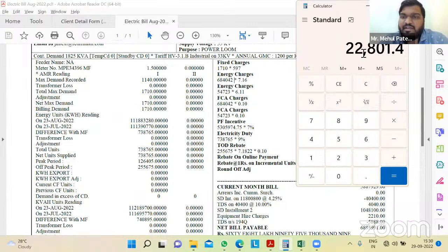So when you divide 22,801 by 4 hours, this is nothing but your 5700 watt peak. Earlier 22,801 was your kWh. So kWh divided by 4 h, the hours get cancelled, and the figure from energy gets converted to power.